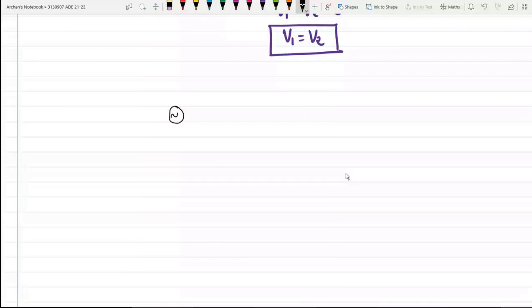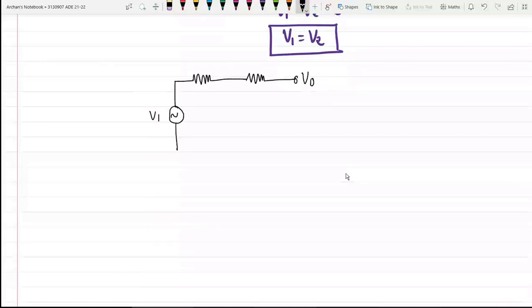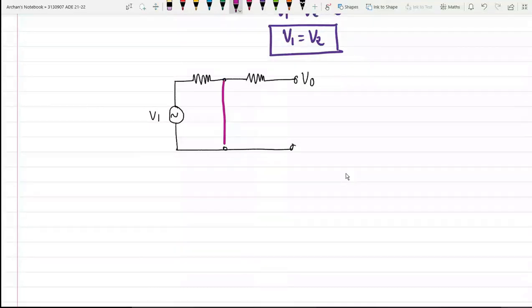Now we will have a forward resistance R1 and a feedback resistance RF, and here I am measuring output voltage V0. So what has happened in between these two terminals? There is a short. Though physically it is not short, we will consider it virtually short-circuited. This is my input resistance, this is my feedback resistance. There will be a flow of current I like this, and because of virtual short, this I is equal to 0.